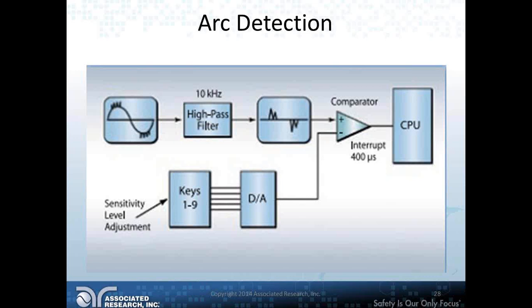Perhaps several products have been damaged during shipping, resulting in poor gap spacing between a conductor and the insulation. This condition may not result in a dielectric breakdown, but with arc detection turned on, it would be possible to catch this problem before the faulty products find their way into the customer's hands.